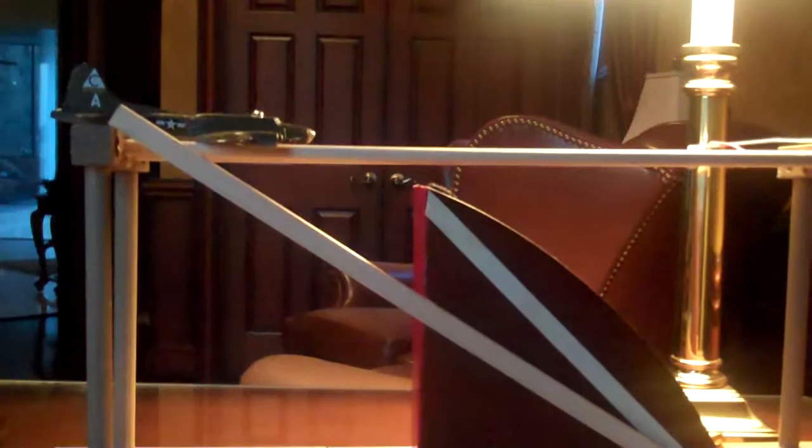Therefore, for each bomb type, altitude, and airspeed, the bombardier looks up in a table how to set the bomb sight up for this. The second piece of information relates to the fact that the airplane will always be ahead of the bomb by the time it strikes the target. The bomb is impeded by forward and upward wind resistance, so when it strikes the target, the airplane is ahead of it. The distance behind the airplane at the time of impact is called the trail, and it is also determined by testing data based on bomb type, airspeed, and altitude. It is also provided in a table.